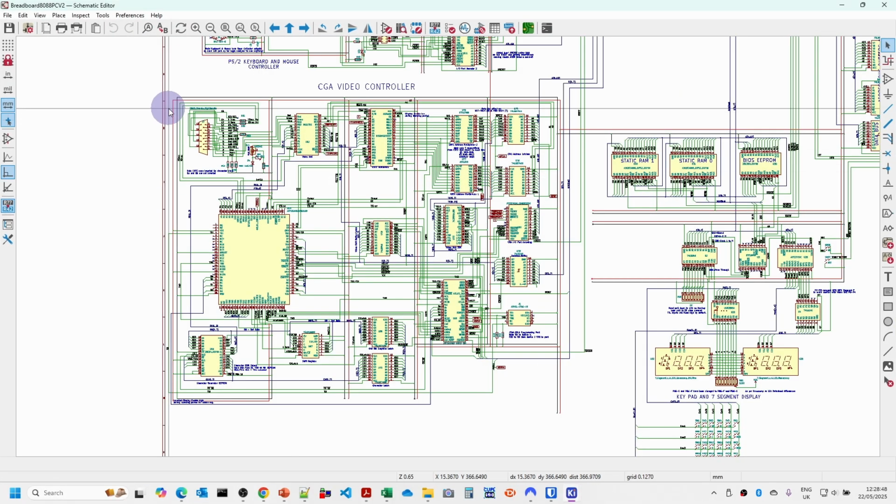I've also got the schematic here for our version 2 CGA video controller, but because this is using a much larger complex programmable logic device, then a lot of the nuances of how these various bits fit together are all buried in this chip. And at the moment I'm just waiting for the 1508 chip to arrive, in that I managed to run out of the number of macro cells. 64 wasn't quite enough to actually do all of this, so I'm getting a 128 macro cell chip.